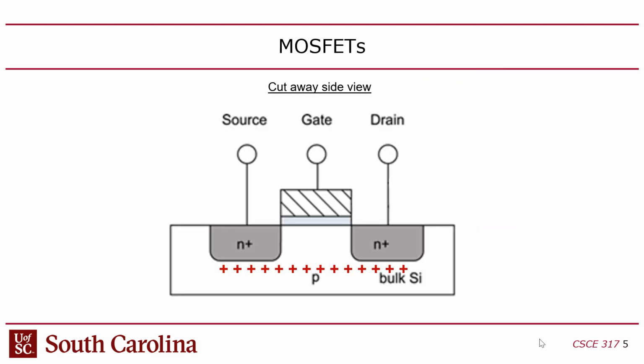So basically, you've got P-type in the substrate. Majority charge carriers are holes, like this lack of an electron. And the N-type has majority carriers that are electrons. The gate has a conductor with an insulator underneath of it, and then another conductor. So what does that form? That's a capacitor, right? And so if you put a positive voltage on the gate,